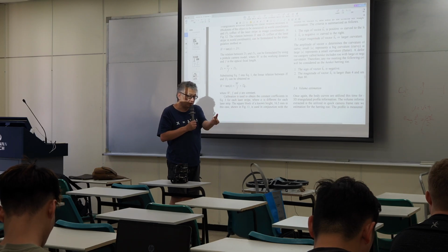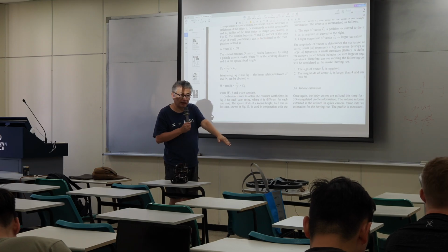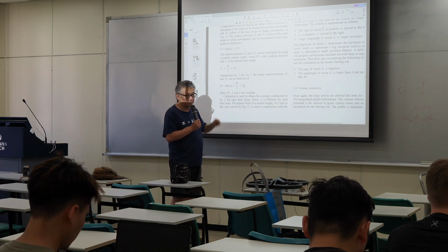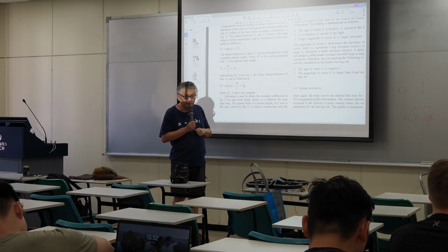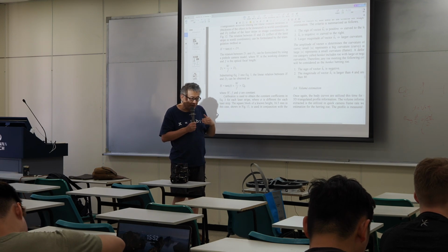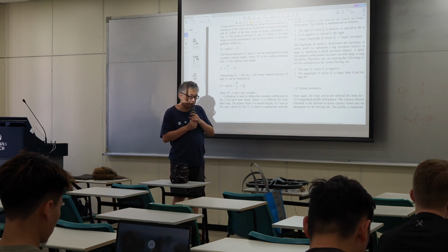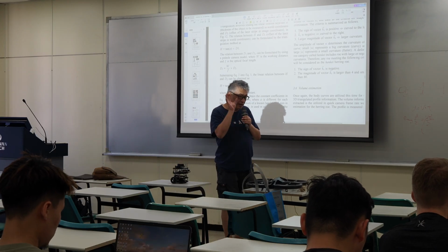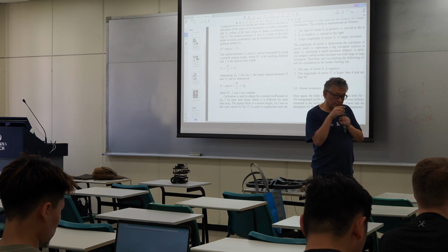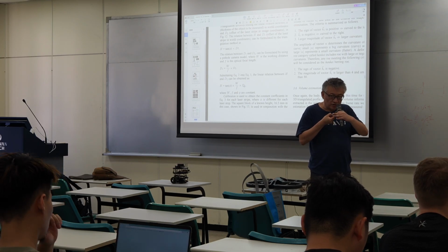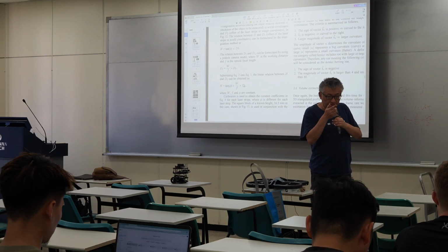For the RGBD camera, it's just invisible light. It's the same thing. They project a light to measure. So first problem, the working distance is a variable. Did the RGBD camera measure the profile? Second, the laser. If you shoot that laser line and project it onto your body, technically they need a focus because there is a lens in front of the laser. So you need to keep tuning it for its focusing.